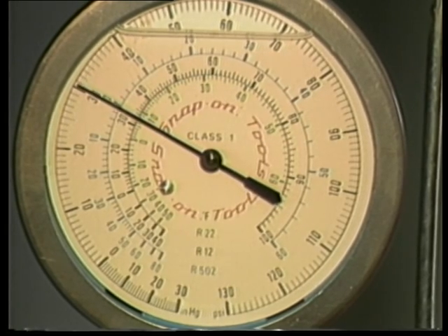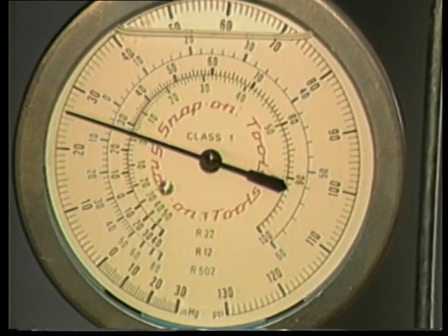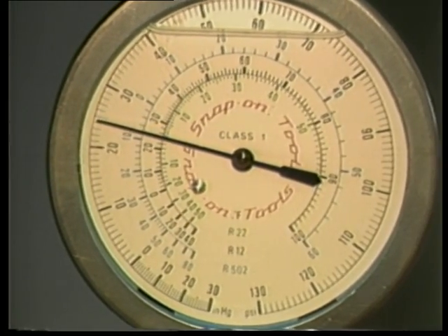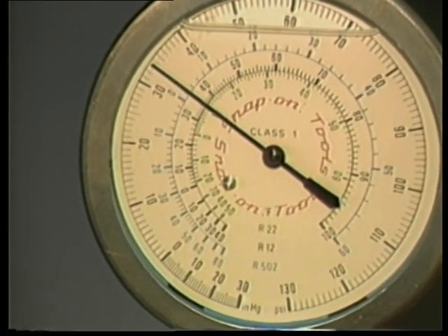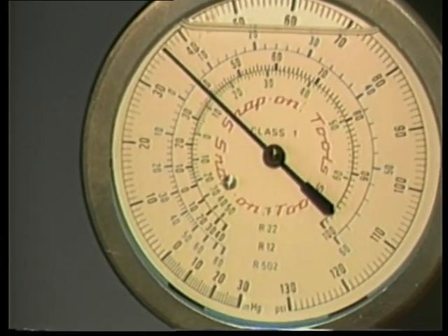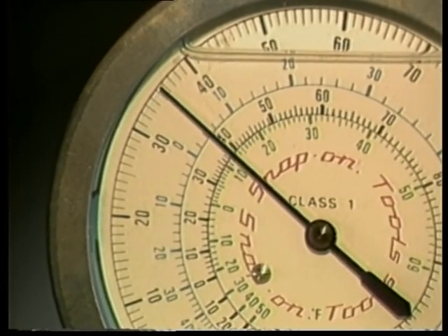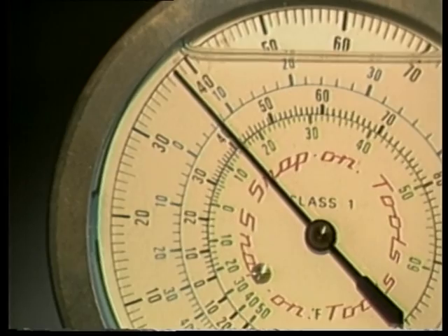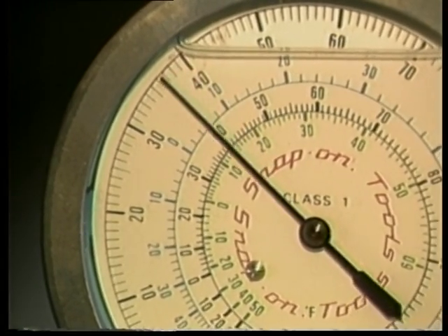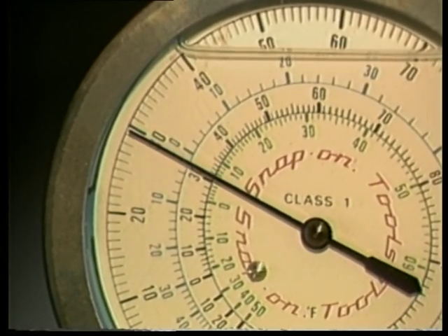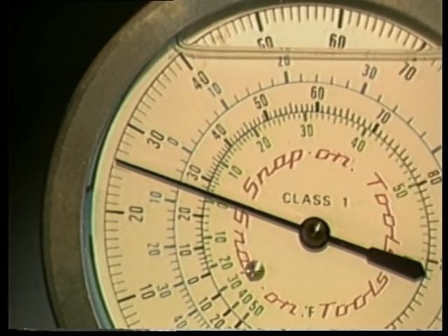Here is the low side gauge on an operating clutch cycling or orifice tube system. Note how the pressure increases to a preset pressure, then decreases. When the low side is increasing, the system or compressor is off. Then, when the compressor kicks on, the suction side pressure decreases. Refer to the factory pressure or troubleshooting chart for a specific make and model vehicle when analyzing pressure readings.